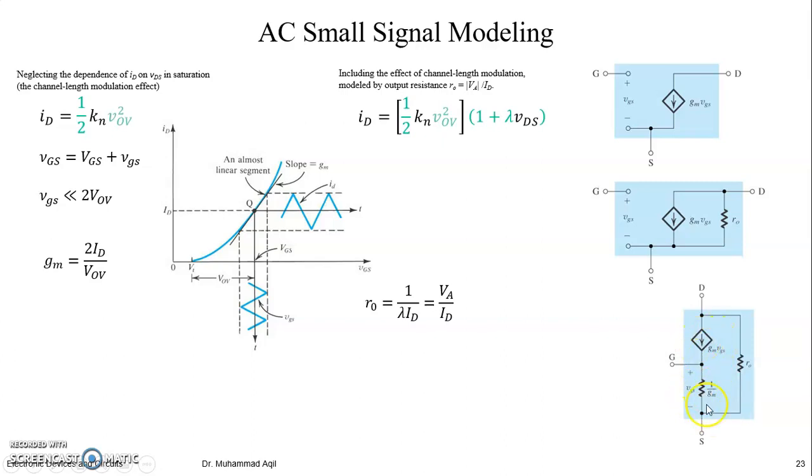Because this current and this current are the same. So voltage divided by current, with current equal to GM times voltage, gives the resistance 1 over GM. Why do we model a resistor here? Because we may include a resistor at the source, and the T model is recommended when you have a source resistor. Otherwise you have to use the pi model.